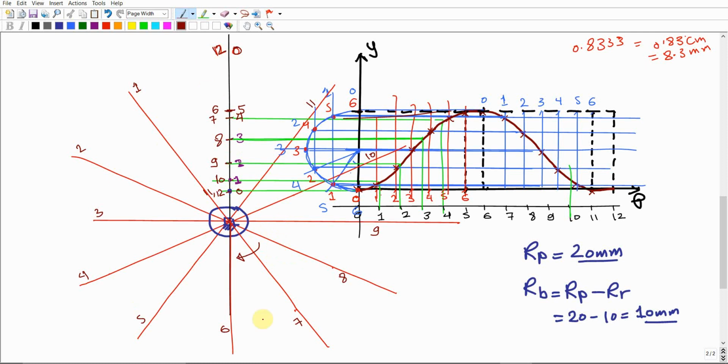So to number these lines, put numbers on the lines in a direction that is opposite to the direction of the cam rotation. If the cam rotation is not given, assume that it is clockwise and put the numbering in the counterclockwise direction.